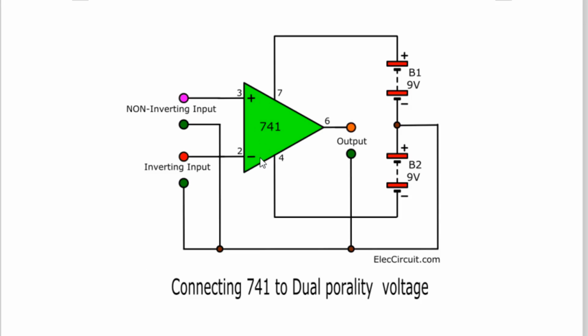Look at this. In an OpAmp, we apply the input either at the non-inverting input terminal, at which time the inverting input is grounded, or we apply the input at the inverting input terminal, at which time the non-inverting input is grounded, or we apply inputs at both, and the input applied is always with respect to ground, and the output is also measured with respect to ground.